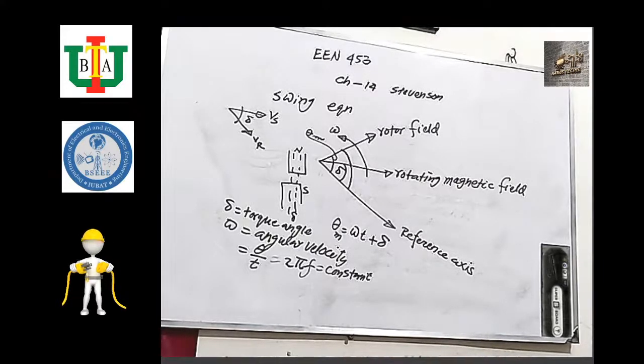Sir, first you said delta is rotor angle. Yes, delta is rotor angle or torque angle, the same thing. You may call it torque angle or rotor angle because the angle is at the rotor. You see North Pole and South Pole in synchronous condition, meaning at constant speed, the rotor pole and stator poles are magnetically engaged, or magnetically locked across the air gap.